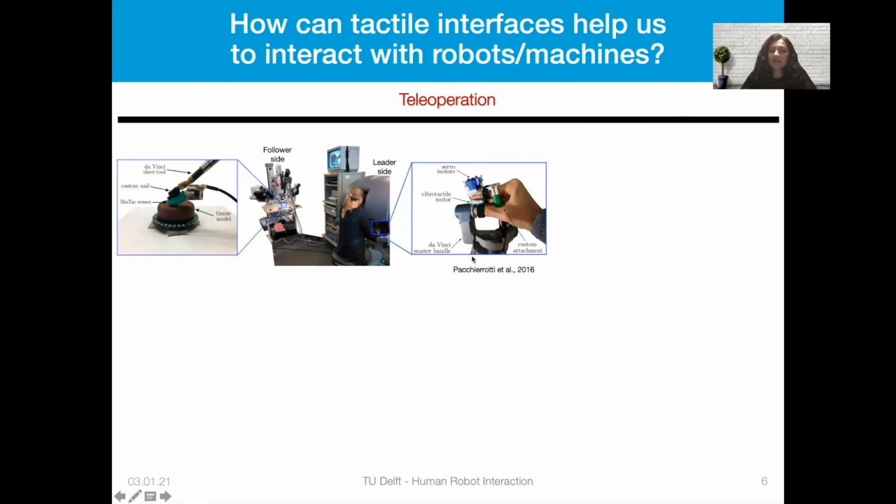However, in this case, these scientists build a wearable tactile interface that can deliver vibration, skin deformation, and contact information to the surgeon, which is sensed from a sensor placed on the follower side. During a palpation task, this sensor can sense the deformations or vibrations that occur on the skin of the patient, and this information is directly transmitted to the user using this wearable tactile interface.